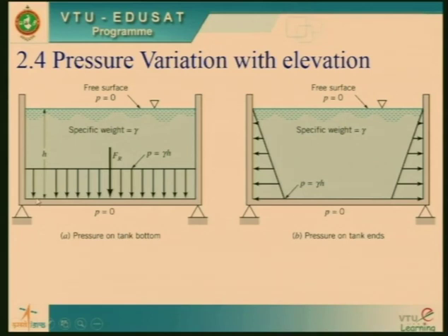H is the height of the liquid over which we are measuring, right. So we can see here, if you see say point A, here also head is say 10 centimeter, here also point B 10 centimeter, C 10 centimeter, same liquid, D 10 centimeter. You can see it is totally a rectangular distribution. Everywhere the pressure is exactly the same, right, like our UDL, uniformly distributed load, correct.